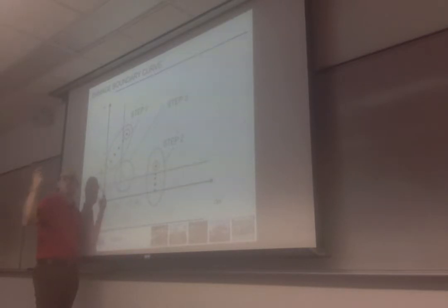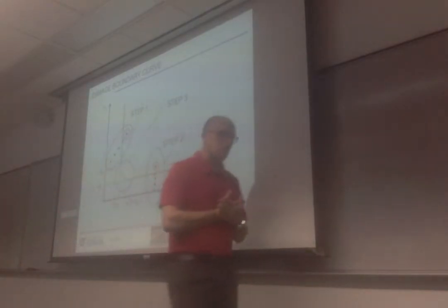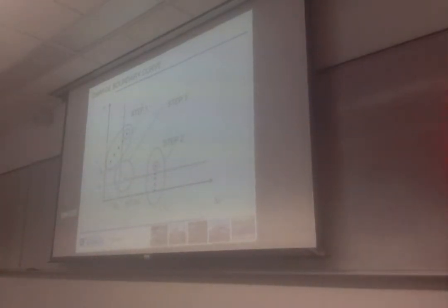Remember, 1 to 3 inches. So the conservative approach is to fix that critical velocity change there. But some people will fix it a little bit higher. Let's say you use one product to do all of this, and then you have damage there. What you may want to do is take a new product, start here, and see what happens, to adjust it. So that will be the first step. Critical velocity change: you use a half-sine impulse, and you drop them from an increasing drop height until you get damage.